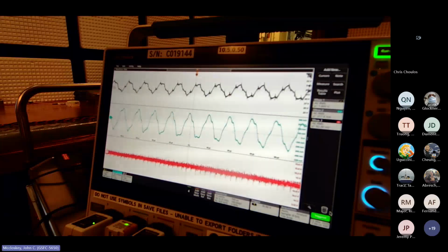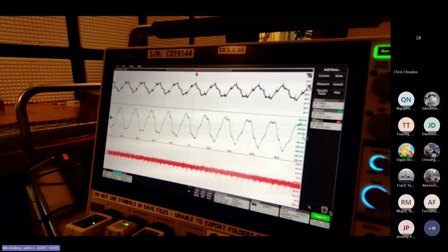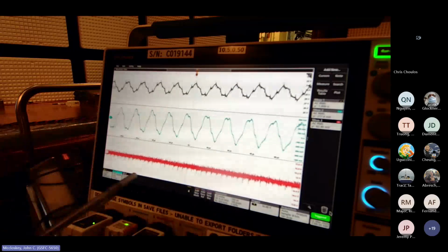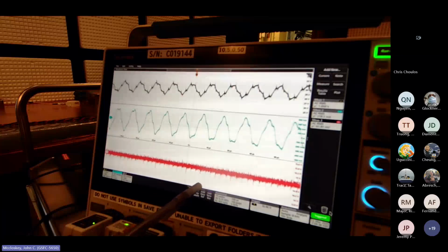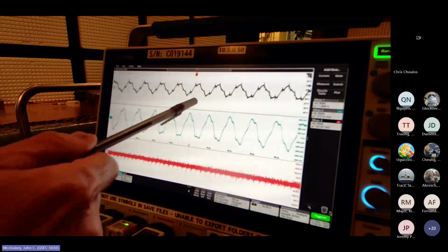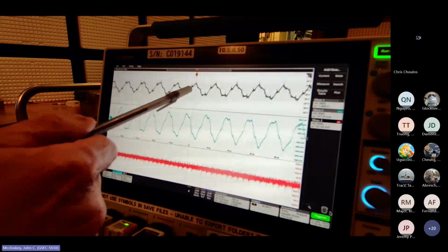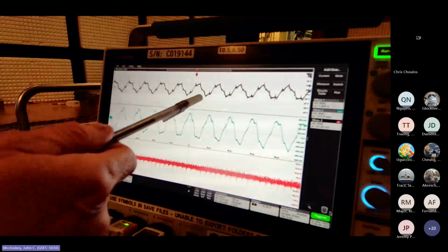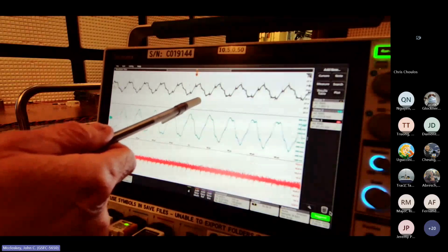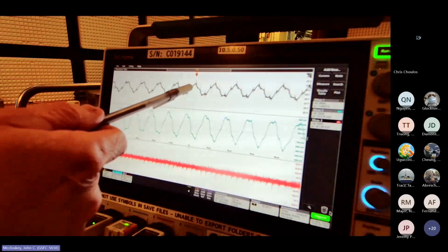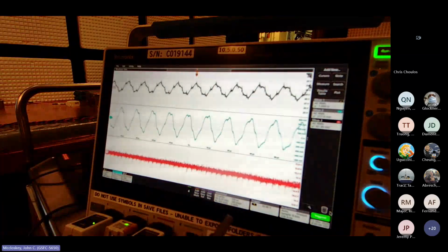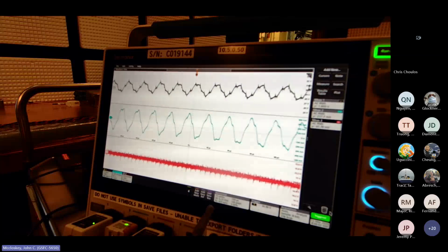The input impedance is going to go down, and the voltage output is still sitting around 62 millivolts. So we're not seeing a lot of the contour of the injected signal, but we're seeing a lot more of these switching edges. And so if you look up here, we have these noticeable, again, this is the input voltage to the converter. That's our 28 volt primary. You've got these ringing characteristics here. Well, if we look at the time base, we're at about 10 microseconds per division.